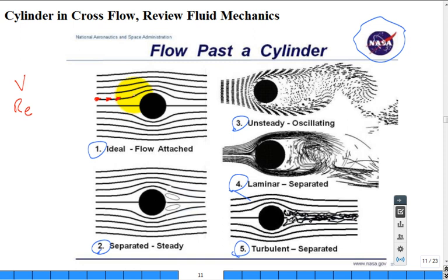But when I get really close right in here, or let me do this one. This one is a special case because it splits and goes around. Tell me a little bit about the flow velocity at that point right there. What do you call that point? Stagnation point. Now that we know the velocity went to 0 at that special point, the stagnation point, tell me about the pressure. Compared to the pressure right here, what happened to the pressure as it went to the stagnation point? The pressure went up.